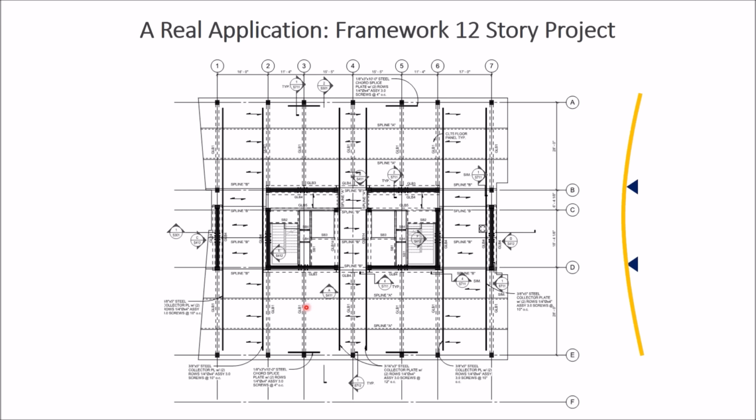So in the east-west direction, this is a cantilever or over 2 support points. In the north-south direction, we don't have those cantilevers, but we have multiple support lines. And so with the cantilever and the different configurations here, we decided to do the more complicated diaphragm modeling.